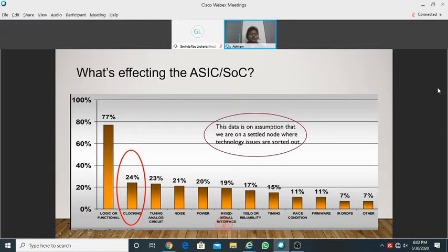And the next point is the analog circuitry. As I have shown you in the hard IPs, there are a lot of PLL blocks, analog to digital converters, and a lot of parallel to serializers and serial to parallelizers. Most of these are technology dependent. So if any issue is there with respect to the technology, then we are going to have a dead silicon. That is where the next set of problems come. And these noise factors are mostly with respect to the analog one. We'll skip this.